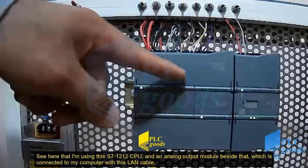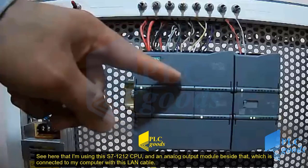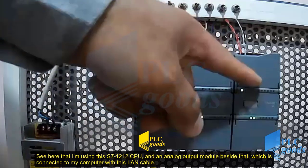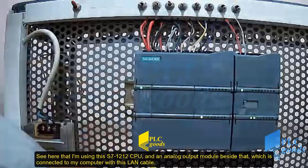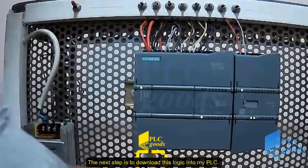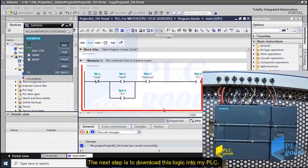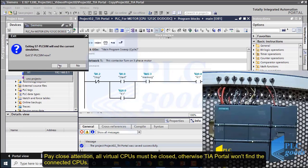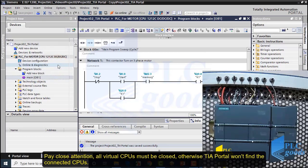See here that I am using this S7-1200 CPU and an analog output module beside that, which is connected to my computer with this LAN cable. The next step is to download this logic into my PLC. Pay close attention. All virtual CPUs must be closed. Otherwise, TIA Portal won't find the connected CPUs.